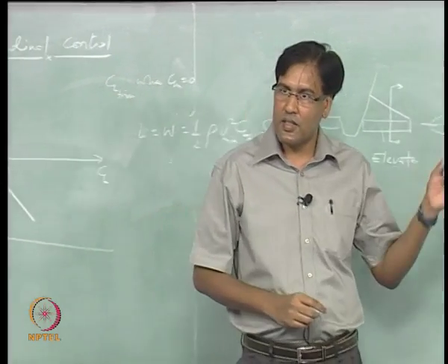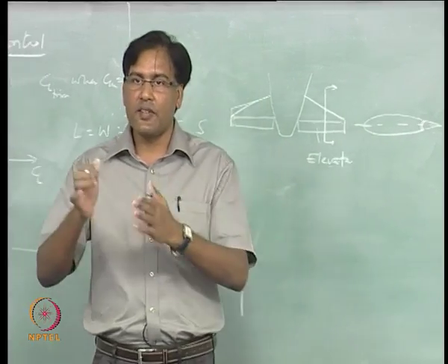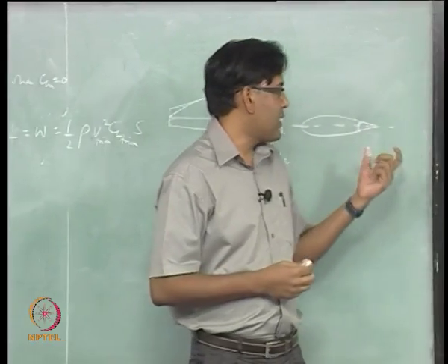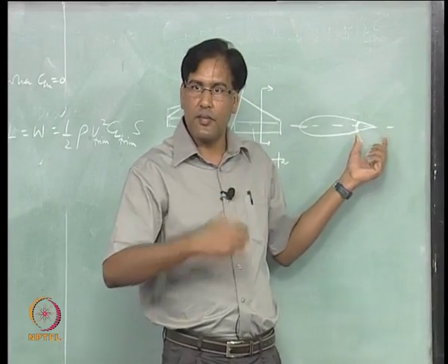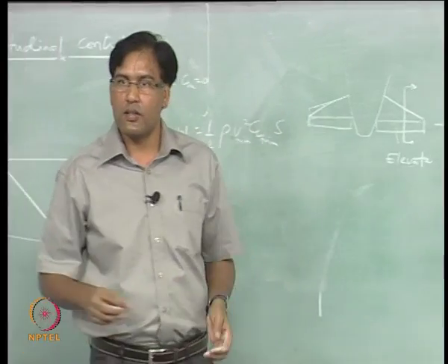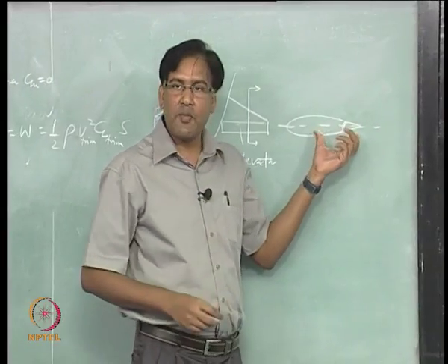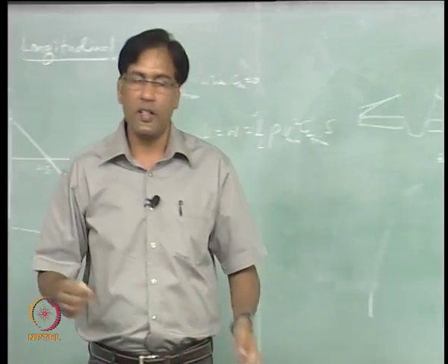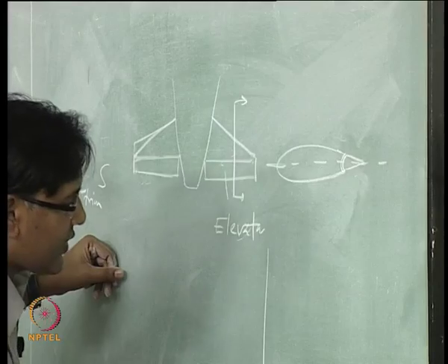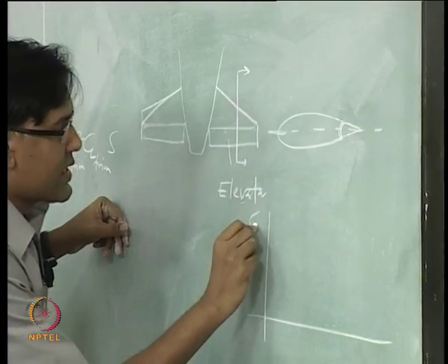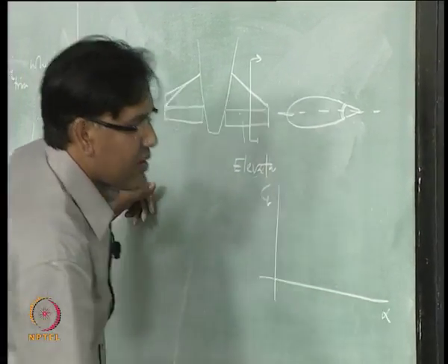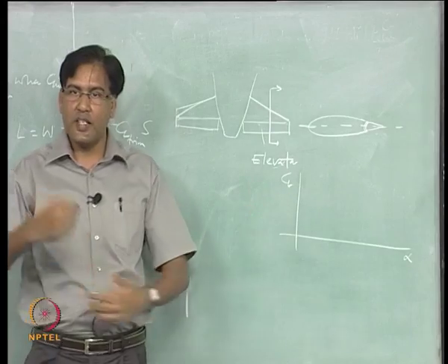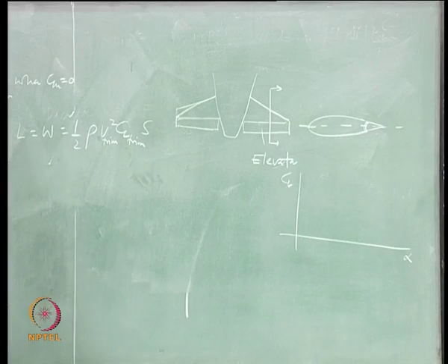So, any control surface or any stabilizer will have a symmetric airfoil, and afterwards using the flap deflection attached to that tail, you are going to change the camber, right. When you change the camber, it automatically gives you a change in CL, right. So, if I want to see how CL is changing when you change the elevator deflection.